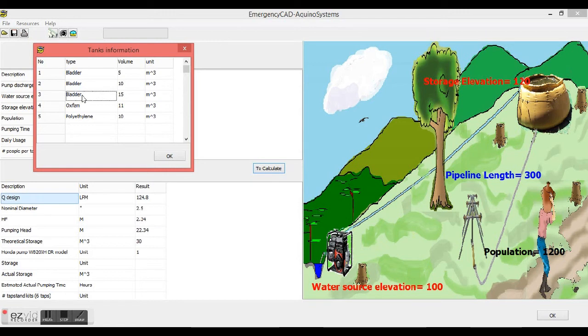Remember that this is an emergency project where we will probably have to use aluminum silicate for the sedimentation of the suspended solids, or other chemicals such as chlorine for disinfection. In both cases, we need to have a contact time to ensure the effectiveness of the water treatment.